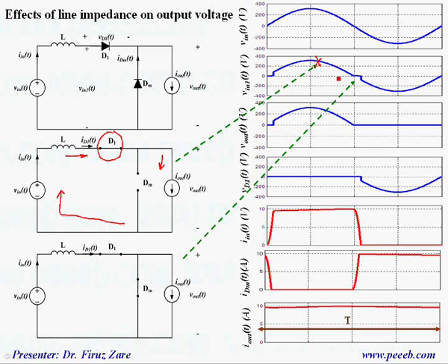So what's happened when the input voltage is getting negative? In this case this diode will be on as well, so there is a short circuit across the load. Over that time we can see that the output current is constant, but if we just concentrate on this node, this current, which is input current, plus current through this diode, should be equal to output current, which is constant.